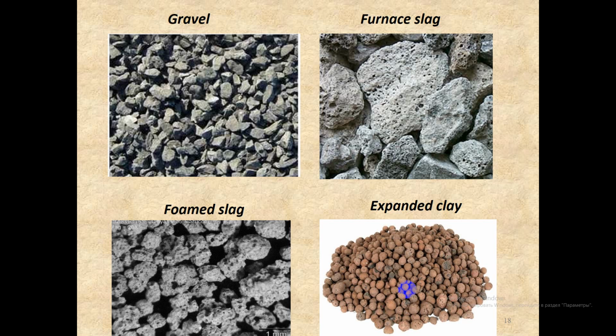If pyrite is in aggregate, it can decompose and this results in staining of the concrete surface. Coal and lignite may swell during the life of the structure and they sometimes decompose. This can leave voids in the concrete.